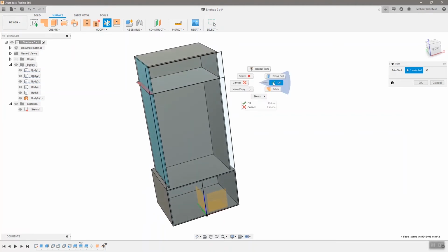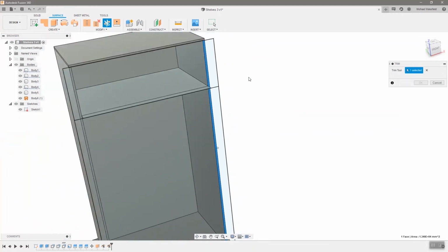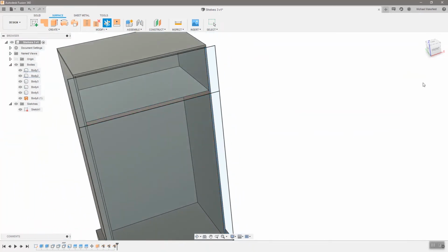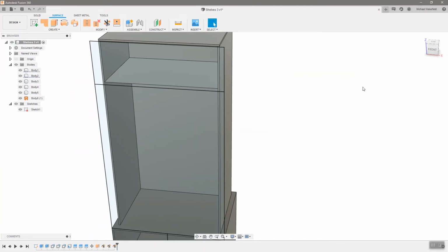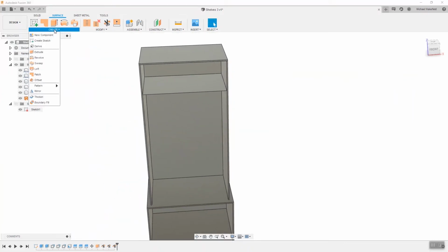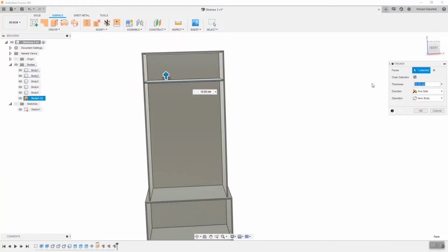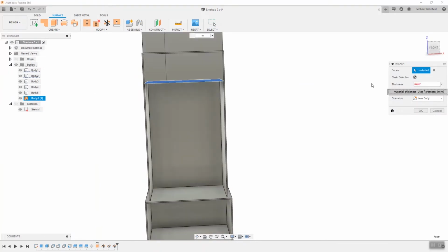It's pretty easy, and you'll notice because I'm using the same command over and over again, when I'm done, I'm just going to press the right mouse button and push up. I'll be able to repeat the last command, and it's really efficient and easy to do that way. Now this surface is only a surface. It has no thickness. So I use the command thicken to thicken this.